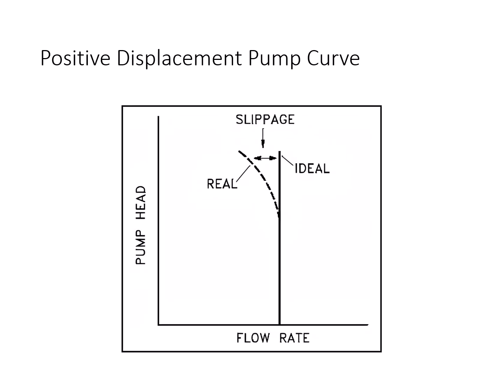Here is the positive displacement pump curve. The flow is almost independent of the system pressure. It shows a vertical or nearly vertical line on the head versus Q graph. Head pressure varies with the system's resistance: friction, back pressure, fittings, and so on.